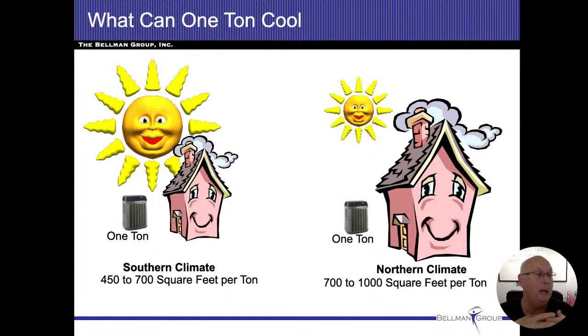So when we look at house systems, we kind of want to get a rough idea if the system is acceptable or not, or if it's too big or too small. The term that HVAC contractors use is a J calculation. They're going to use the location of the home, and they talk about how many heat days we have. They're going to look at the amount of insulation, the square footage of the home, and how many windows there are.